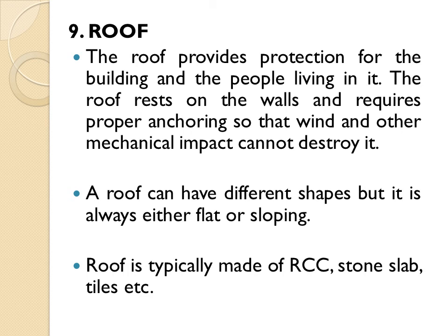The roof can have various shapes, but they are broadly classified as either flat roof or sloping roof. A roof is typically made of RCC in an RCC frame structure, it may be made of stone, or it may be made of tiles. So again depending on the functional requirement of the building, we have to choose a particular type of roof.